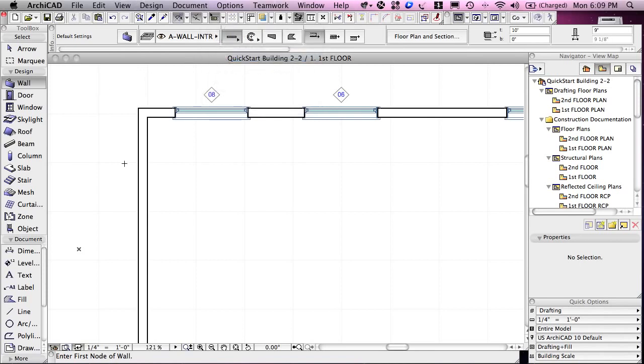Now if I go to the edge of the wall here, you'll see this is the 10-foot snap point, but that's measuring on the outside. If I go to the inside, you'll see a snap point measured. Let's just compare them. You can see that there's one here and one there. This is the one that's 10 feet clear space. So you should definitely measure along the edge that will give you the correct distance that you need. Now I'm going to click to start placing this wall.